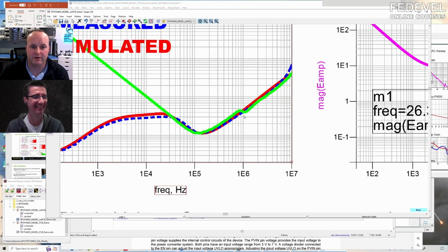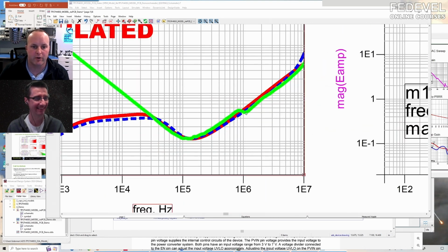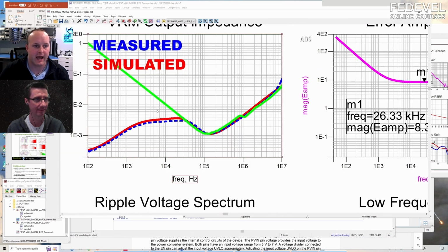And so you can see right there in the off measurement, right? You see there's a clue already. I have a little bit of a 1 megahertz dip there, right? The clue was already there for me, right? So why don't I see that in my simulated measurement? The answer is because in this simulated measurement, remember, I'm not using the board effects, right? So I don't have an inductance.